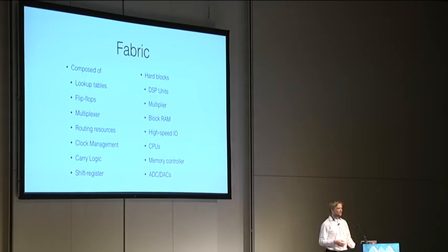Usually you will also find some clock management things like a PLL, where you can input a frequency of 10 megahertz and get out a frequency of whatever you like, usually 20 megahertz or something like this. Then there's also carry logic, which helps you to create faster multipliers and adders, which is very important, and shift registers, which are used for shifting a bit to either direction.